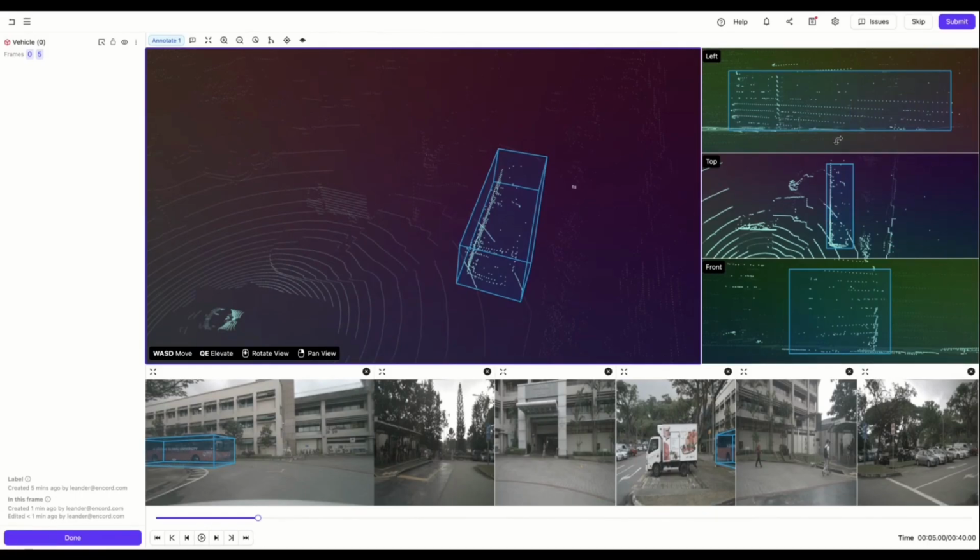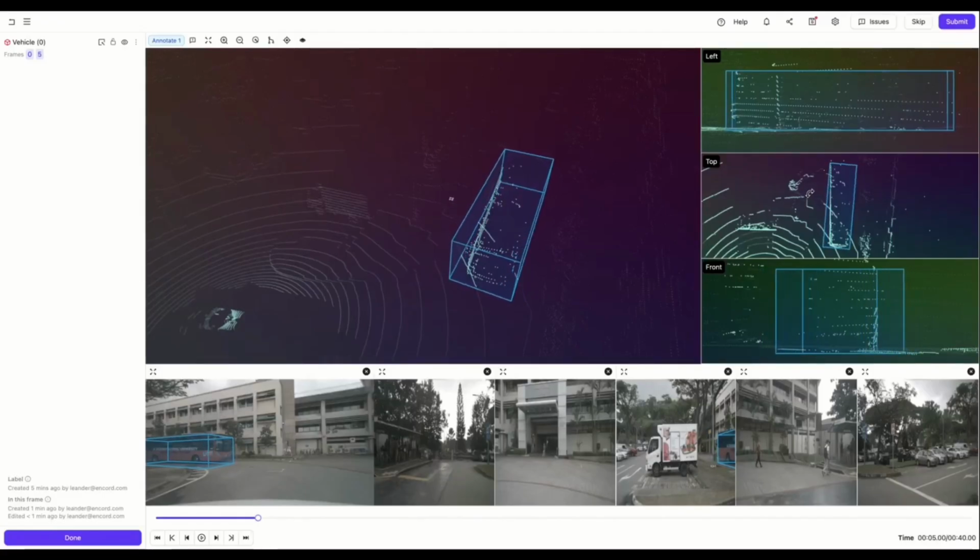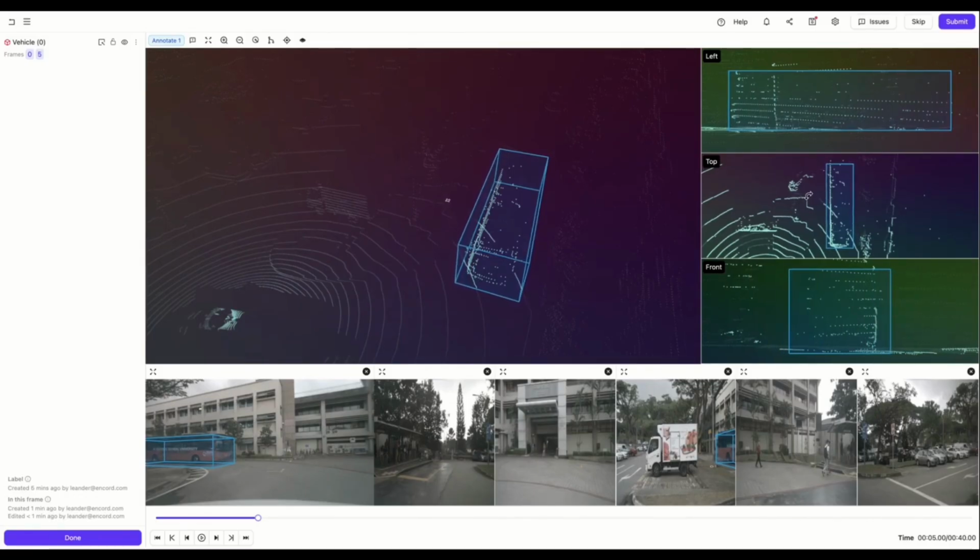One other thing that I can do within this left top and front view is if you look at the top view, now I'm hovering over the cuboid itself. If I move my cursor just outside the cuboid, you can see the cursor's turned into this kind of bent arrow. And so if I hold down left click and drag my mouse, I can actually spin the cuboid on this axis. So that can be really useful if I'm pasting a shape onto an object that doesn't quite align.